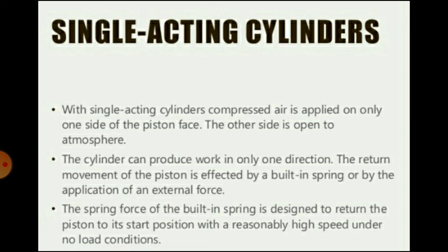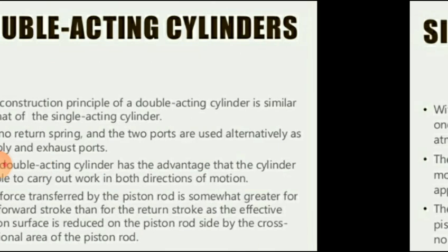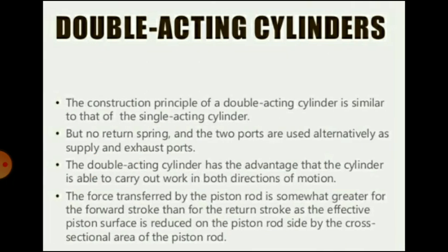The spring force of the built-in spring is designed to return the piston to its start position with a reasonably high speed under no load conditions. Then double acting cylinders. The construction principle of a double acting cylinder is similar to that of a single acting cylinder, but there is no return spring, and the two ports are used alternatively as supply and exhaust ports.